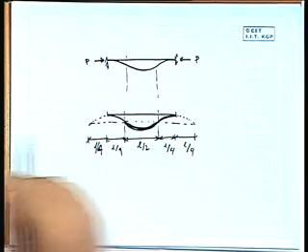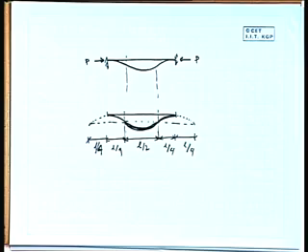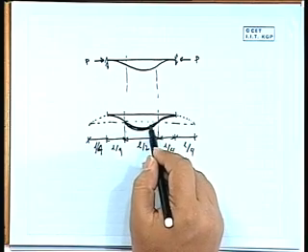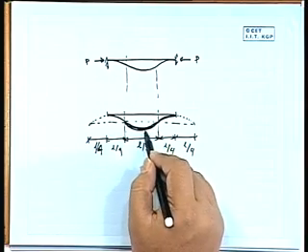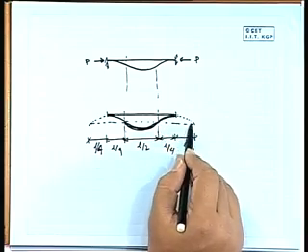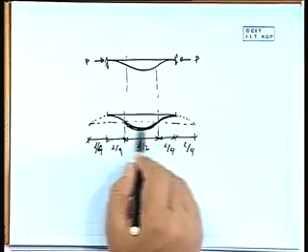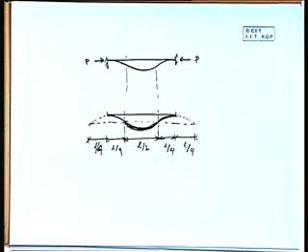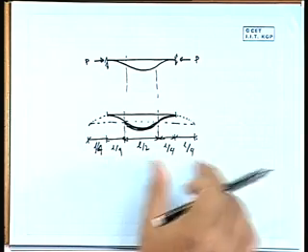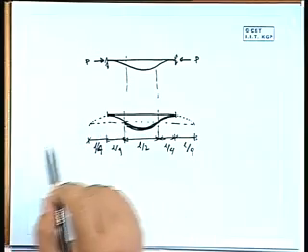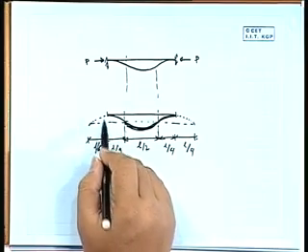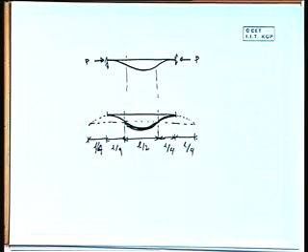Now this part is just like a fundamental case, because here slope is there plus, and this part is also the fundamental case. So it is L by 2, this is also L by 2, this is also L by 2. Right. So there are 3 representative parts, each having a length of L by 2, and at both the ends some slope is there, plus it is symmetrical with maximum amplitude at the middle.